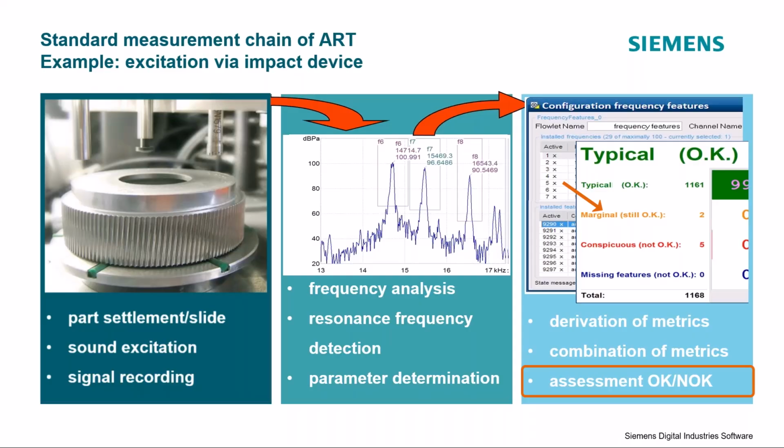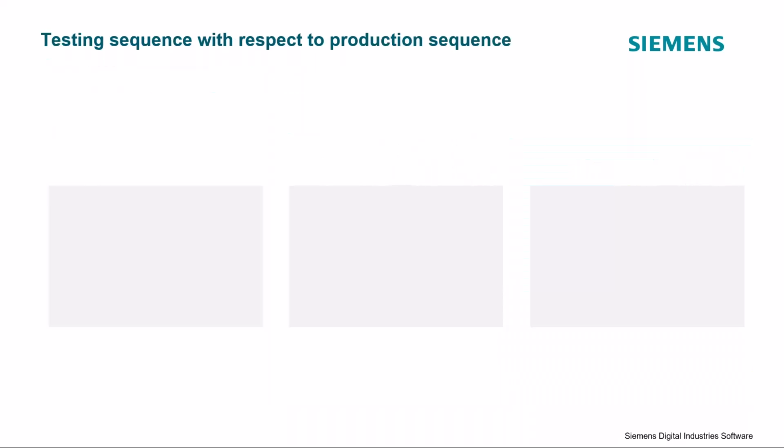Well, you can skip it, but many of our customers keep it, because if you have a production line and you see that more and more parts go into the marginal range, you see that some of your production parameters are drifting, some wear of a tool, some furnace temperature, some pressure or anything, then you can react. You're able to react even before the scrap rate starts to increase. That's the reason why they have it.